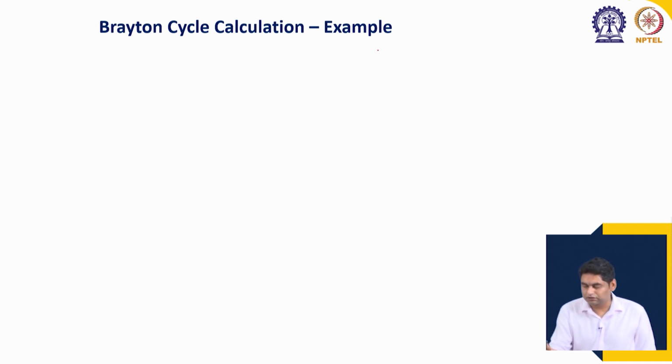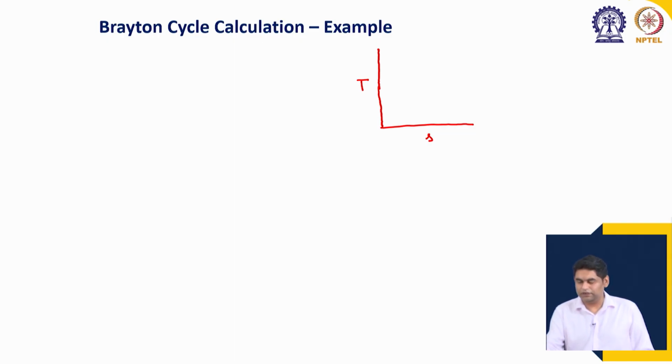Let us draw it on the right hand side. This will be the first step for solution of all types of gas turbine problems, because this gives us the idea of how the cycle proceeds. Now, we have the 4 processes going from 1 to 2. Remember the important thing that we have discussed, that we will not use the expressions derived previously as formula. We will start with first principles and try to calculate the value of temperature, and if any other variables are required at each of the states, okay, after each of the processes.